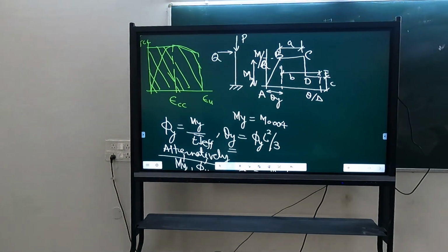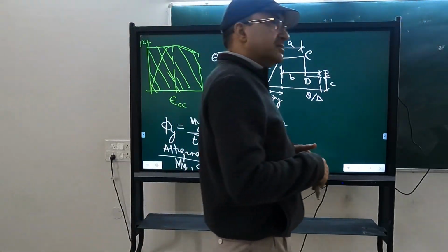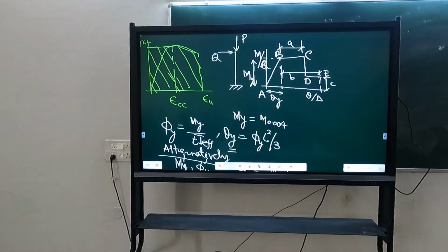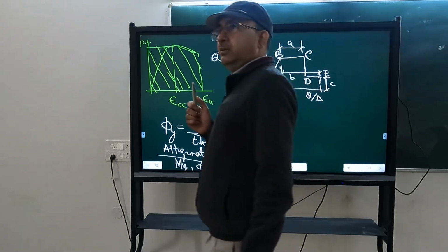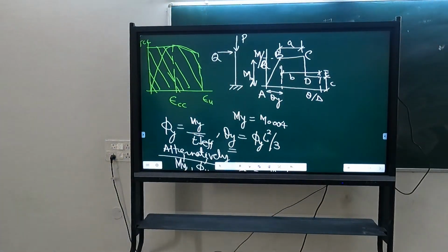Okay, because it is the elastic range. So here, monotonic or cyclic backbone curves are the same. Okay, the difference will occur beyond B. And what is the difference occurring? The strength is reducing and ductility is reducing. In addition to that, there is reduction in stiffness and pinching.